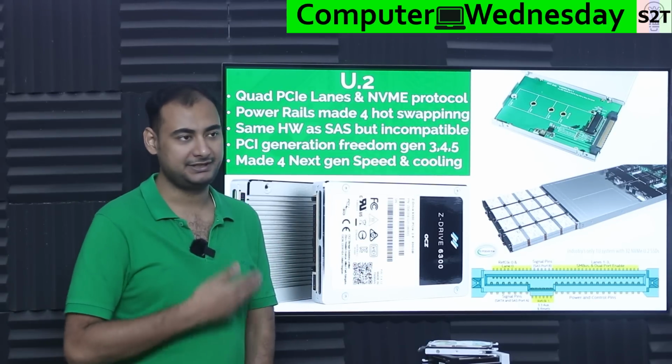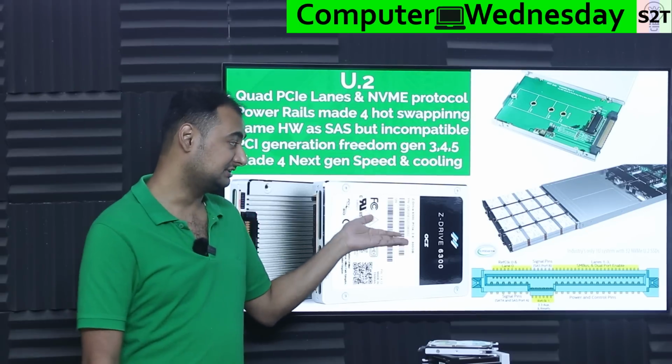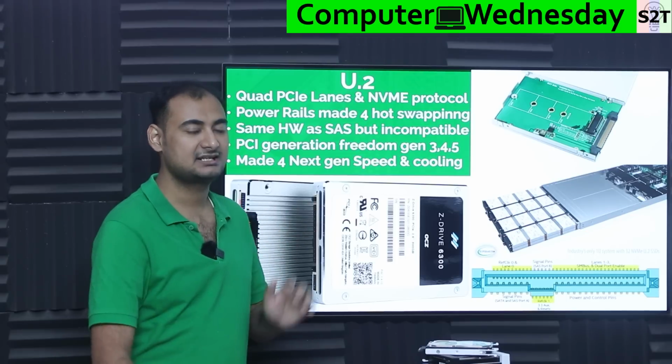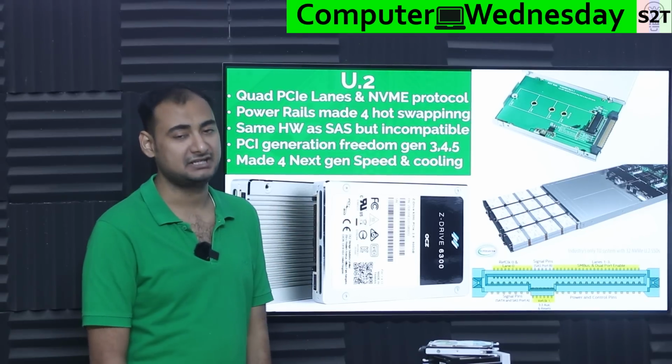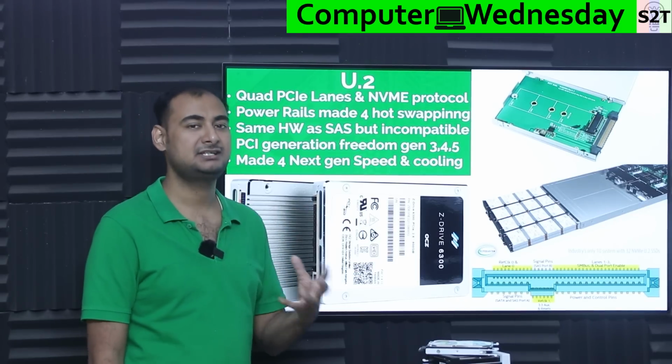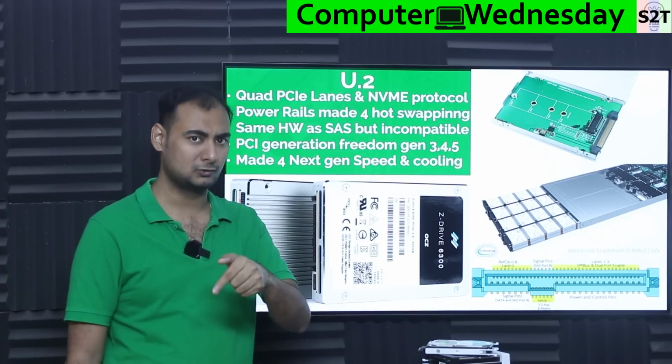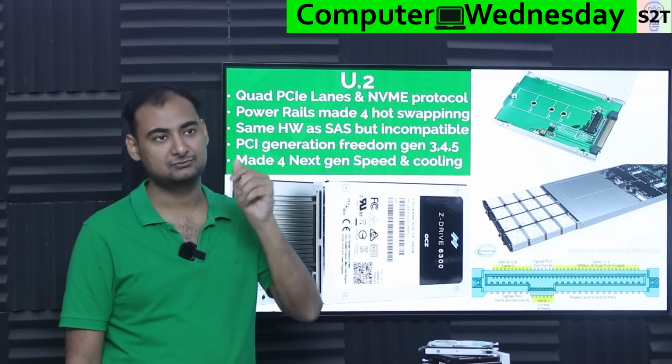Most of the time your OS is barely putting enough load. But when you're talking about these sorts of things, they could be loaded to a point where the queue depth, basically how many requests it has piled up, would be very high. So it will heat up. You need to design in such a way that it can handle the heating. That's why they even have cooling fins or through holes, meaning the actual NAND flash can get fresh